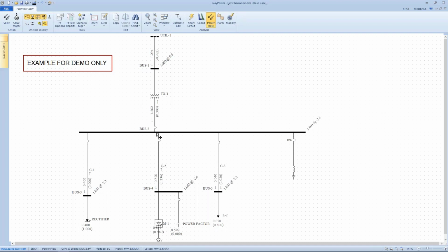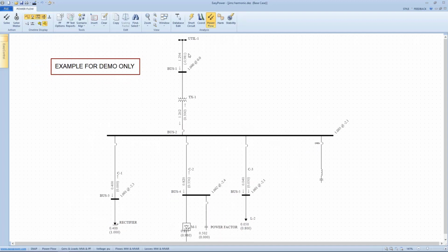I can see that we actually have a reverse situation, because now there's not nearly the reactive power being demanded by the motor, and with the capacitor still in the circuit, I'm actually generating a reverse condition where I'm supplying reactive power out to the grid. Not something that the utility normally likes, but they'll potentially live with it if I don't stray too far from unity. Nevertheless, the question is, what does that do to my harmonic distribution in my system?